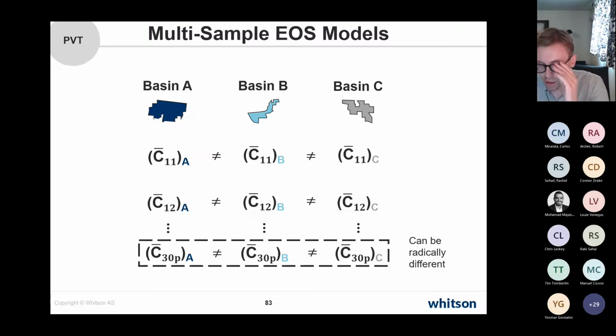So a field average aromaticity or paraffinicity relationship is very correlatable to the thermodynamic or PVT properties of that component. So for each of these individual basins, our job is to estimate these properties for components heavier than C7, which will be field-specific component properties, typically going up to C30 or C36 plus.